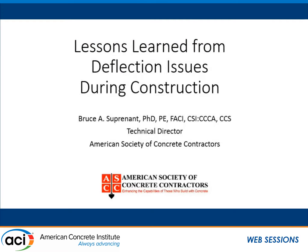First of all, I'm really glad all these other guys did all my work for me, because that's going to make my life easier. Second, I agree. The construction loads are a big issue when you try and do deflection calculations. What they haven't said yet explicitly is most of the design software doesn't handle construction loads very well. So if you're getting deflections off of design software, these gentlemen were using a little different special program and running it twice. You see a little differences, so you have to be careful when you're using design software,